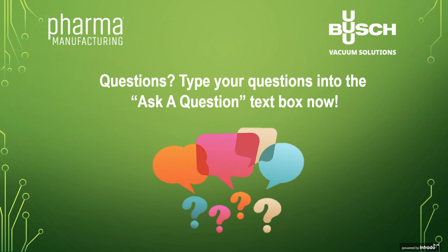It sounds like somebody's throwing nails in a dryer. And what the anti-cavitation valve is doing is, you could either have one that's just open to the air, so it allows the pressure to be increased, or if you have a process that you can't introduce air into, we can also take the motive gas that's coming out of the discharge separator, recycle that back, and then use that to control the pressure as well.